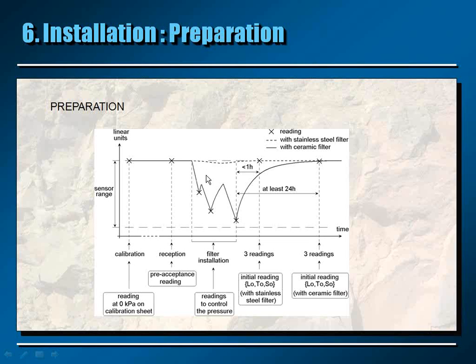And once the filter has been installed, it is important to wait for this pressure that was created in the piezometer to dissipate before taking the initial readings. You will note that this dissipation is quick with the stainless steel filter, less than 1 hour, but can take at least 24 hours when you are using a ceramic filter. So it means that you need to wait at least a day before taking the initial reading after having installed the filter.